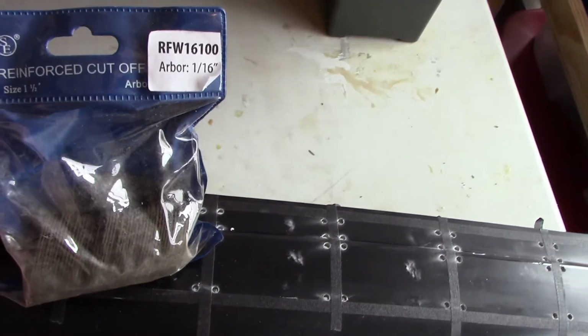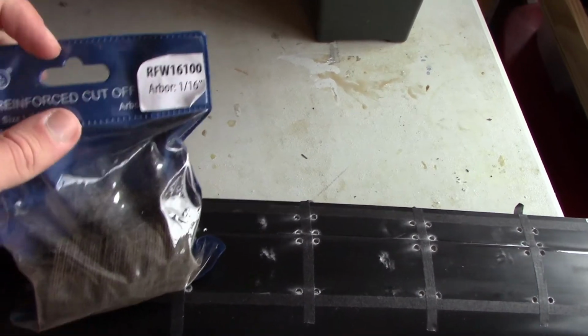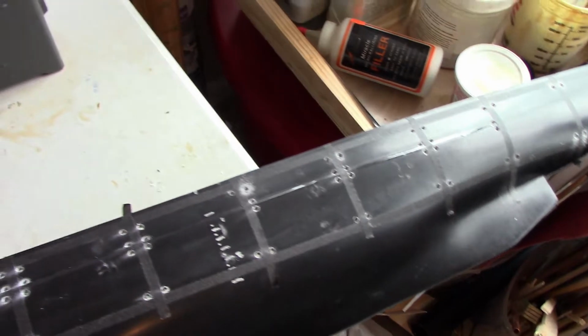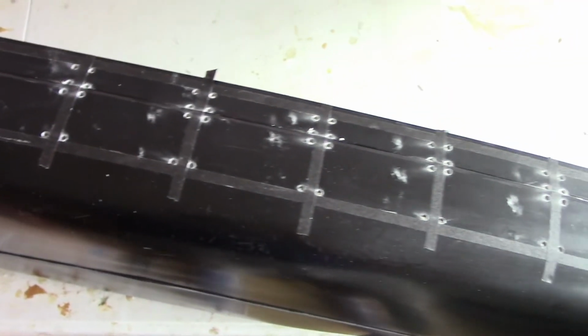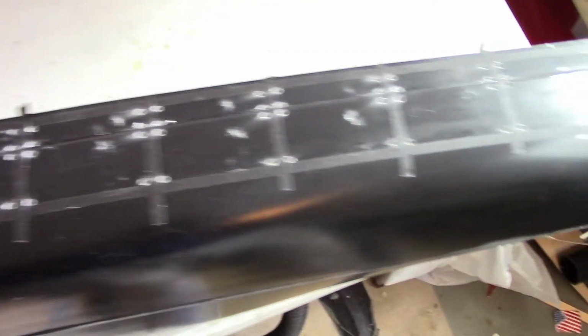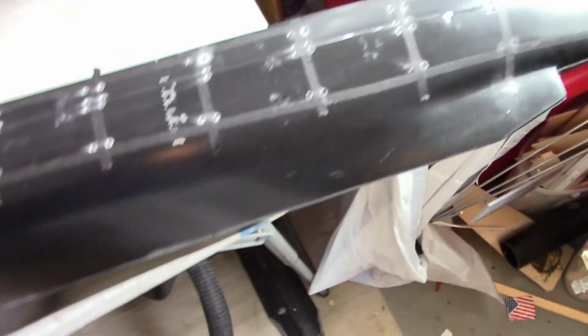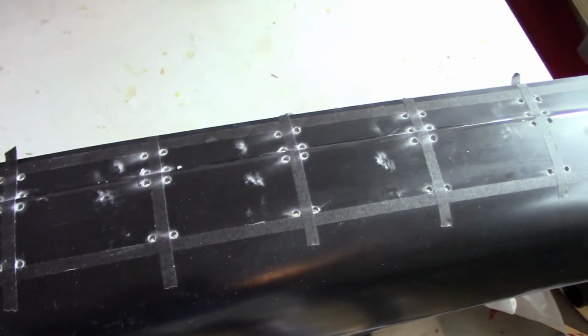I build a lot, so I go through a lot of cutoff discs. I don't know if this was a pack of 100 or what, but it was a lot. It's lasted me a while. Going through this process, cutting out the hull, usually expect to go through 2 to 3 cutoff discs because they wear down as you cut more, and then sometimes they'll shatter, which is why the eye protection and the face protection from the respirator or dust mask help. Over the years, I've been hit in the glasses and on the respirator with the wheel flying off sometimes.